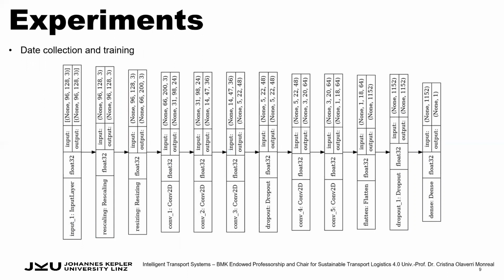It is very simple. It takes an RGB image as input and eventually outputs a float number, which is the steer angle. The road was initially fully covered with snow, and the car tracks of each lap of driving were kept during the data collection, and therefore they were also captured by the front camera of the car. And as explained earlier, we only use video recordings and the steer angles for training.